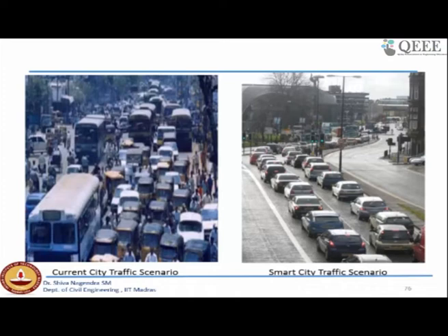When you use this information from the emission estimation, you notice that this will contribute, say, about X tons per day. Because of this X tons per day, in this particular area where you measure the pollutant concentration, the concentrations are 200 microgram per meter cube. If you recollect, the particulate concentration as per the National Ambient Air Quality Standards is 100 microgram per meter cube.